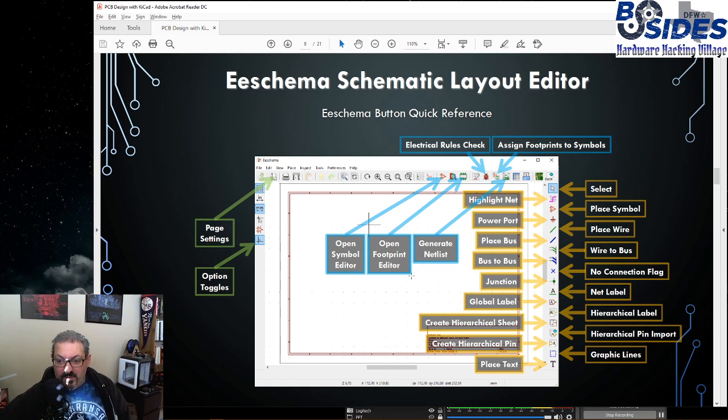Now the sheets are not connecting components by default, and that's where we're going to have to use our hierarchical pins, to pin where in the circuit on this section it's connecting to the circuit on that second page. So this is only really used in larger designs, but it's a useful way to expand a schematic beyond a single page. So instead of having to go to some really large piece of paper that's going to be unprintable in a paper format, you can have multiple pages that detail different parts of the schematic and then link between them.